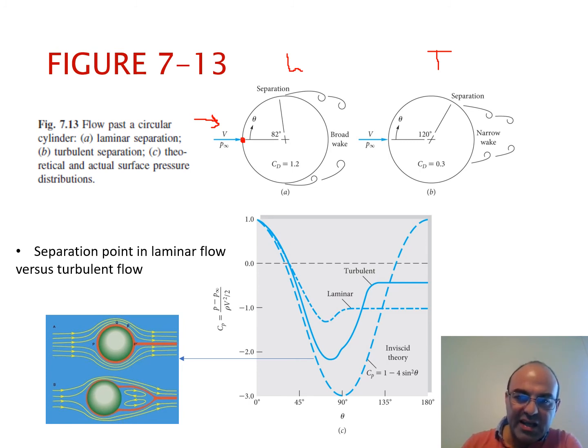Then a boundary layer forms. So if you look at this picture here, the flow stops at this point, and then a boundary layer forms on the surface of this cylinder. Even in this theoretical assumption, or in the actual case, at the front of the object, the velocity field or the streamlines look kind of similar. If you look at the first half of it, they look similar. The difference starts at the back, downstream of the flow.